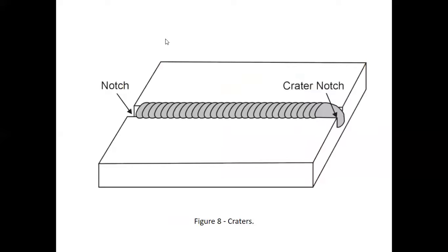Okay, so a couple things we're going to see when we get back. We talked about the stringers versus weaves padded plate that we're going to be doing. So this is a weld. This is a butt weld here, but this weld is weaved in. And a couple of things we see here is a crater notch at the front, or this is the back, sorry. They started here, they welded this way, and they didn't quite fill up the end. They yanked that rod out of there before it filled up. We can see that square wall right here, and we know there will be a square wall right here. That is going to be what we want to avoid.